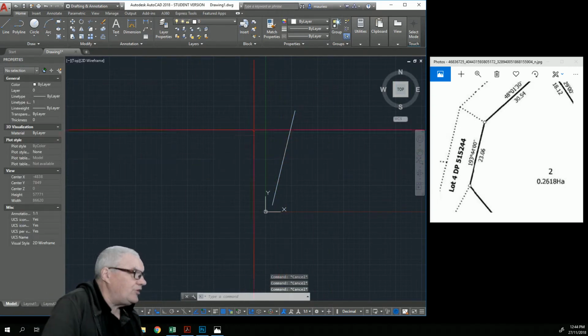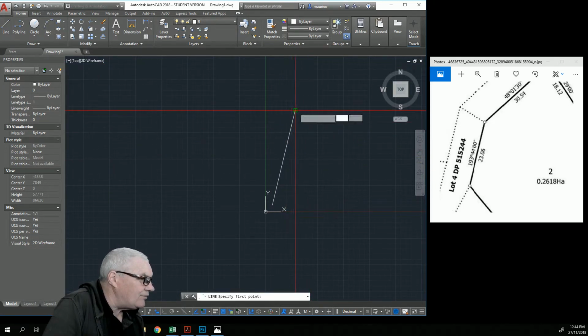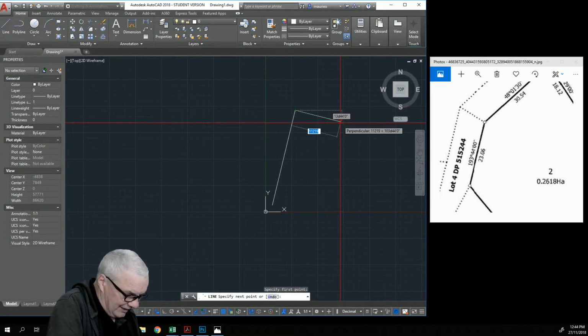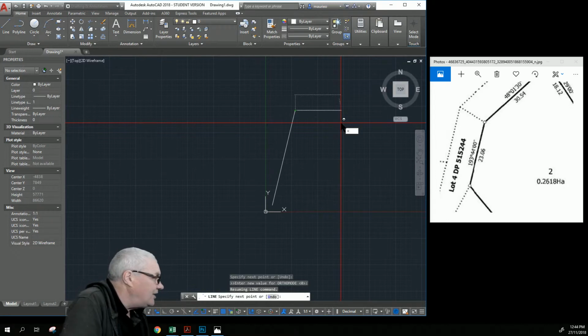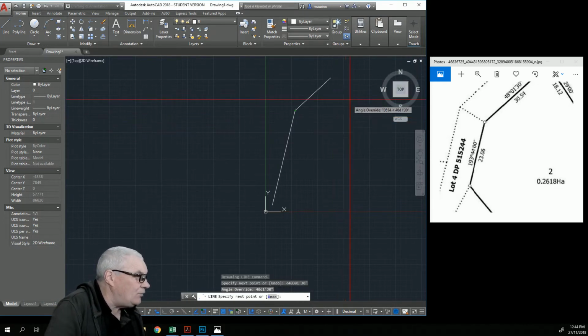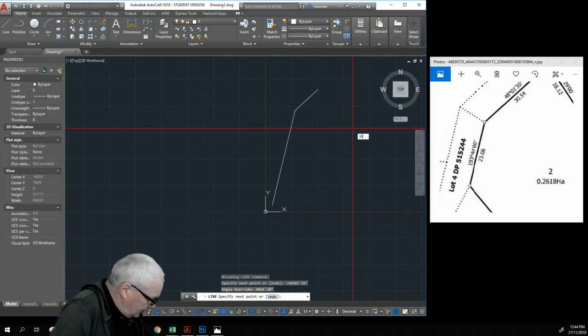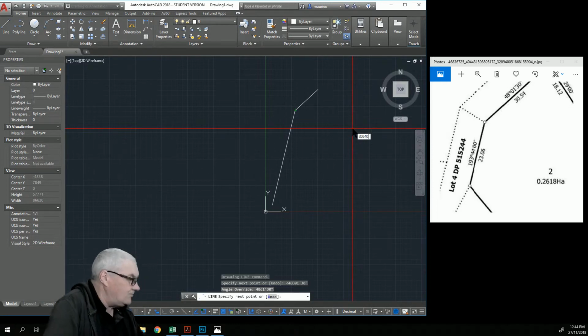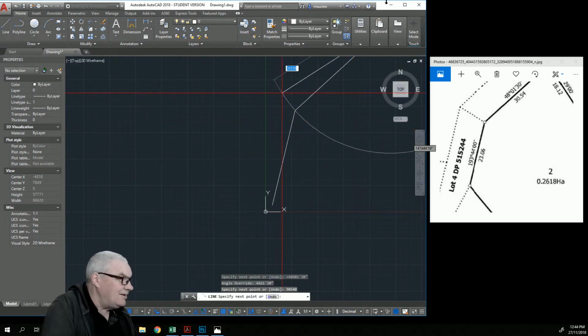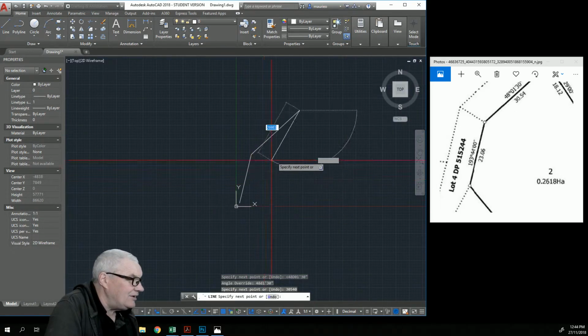Alright, now it's on to the next line, which is here, going from that point there. Again, shift with the chevron, and 48 degrees, 48 D for degrees, 01 minutes, 30 seconds, enter, and there's our angle override, 48:01:30 for 30540 millimeters. Okay, and that's that one put in there.